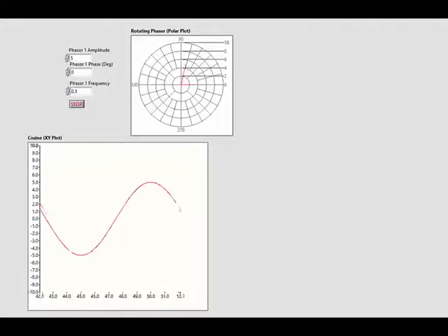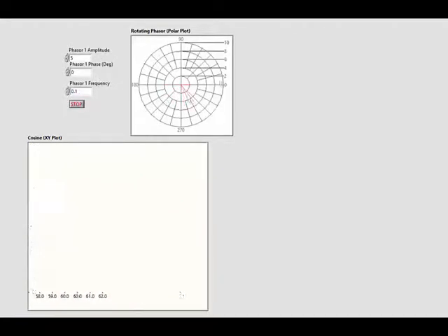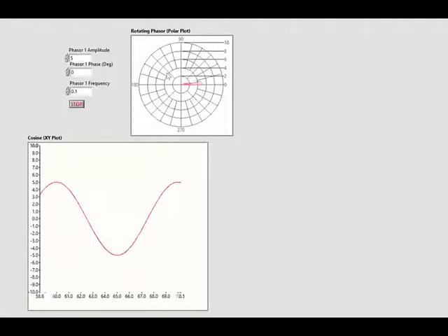And then finally we've got the phasor frequency. This one's new, we haven't seen it before because we haven't seen a rotating phasor, and how this manifests is the speed at which the vector rotates on this polar plot. So I'm going to change some of these quantities. I'm going to change the amplitude and the frequency so we can see how they manifest in this diagram.